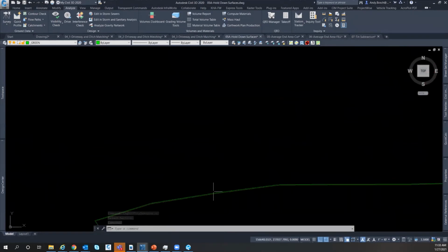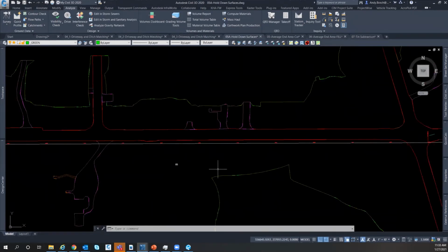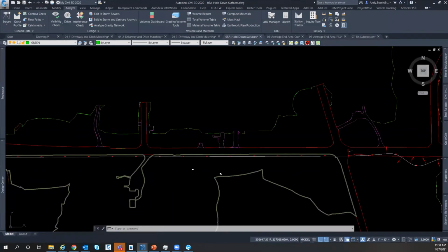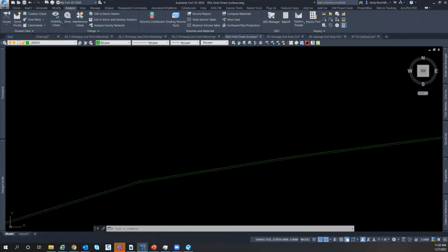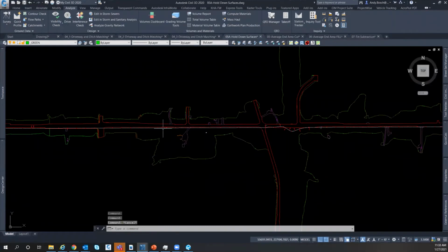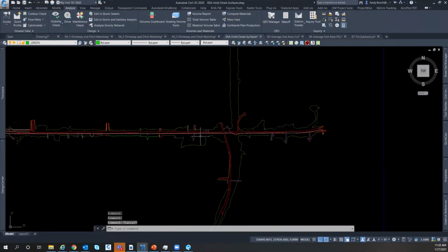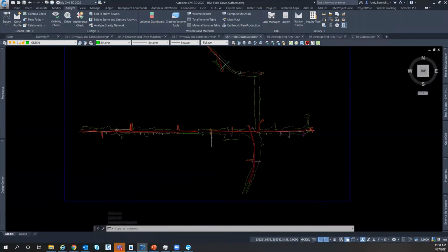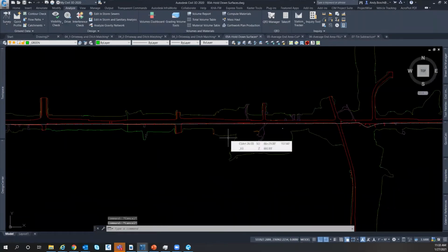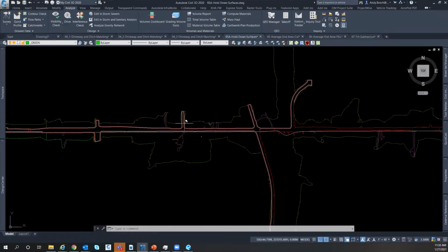The big thing to think about is define your given areas, make polylines out of them, make boundaries, offset those polylines, and then give all those polyline areas a given elevation, and then start pasting those polylines into a surface, hide them, and then show them again so you get these individual areas. And then it's just a tin comparison from there. And you'll get yourself a really good hold down surface to utilize for your earthwork analysis.